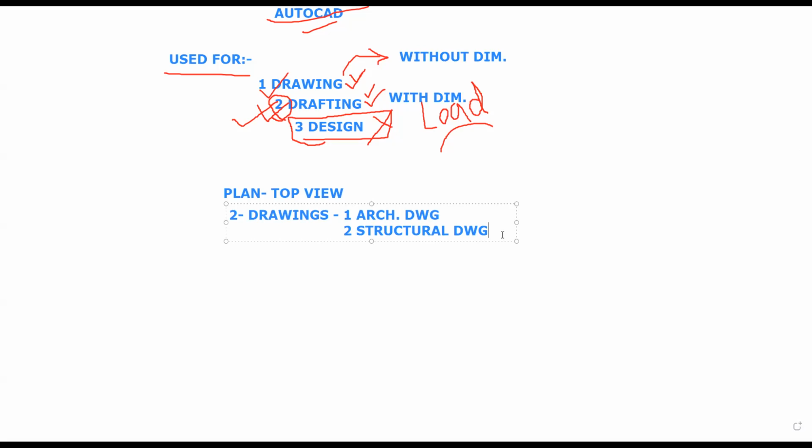For detailing, actually there are two methods of detailing. One is ductile detailing, which is very famous and used worldwide. In terms of India, nationally, there is a code book for ductile detailing, and ductile detailing gives you the basic rules that you must follow while designing a structure. So it is very important to know some rules before going for your software. Okay, all right. Let's proceed with other things in this.